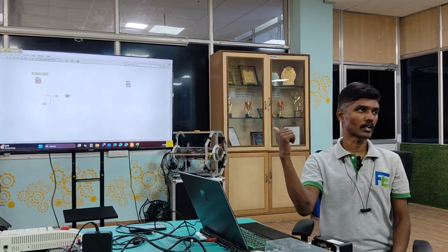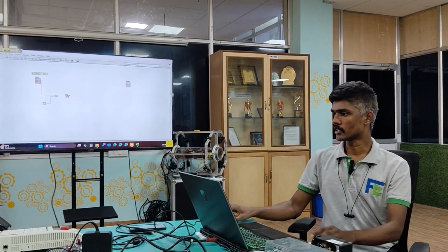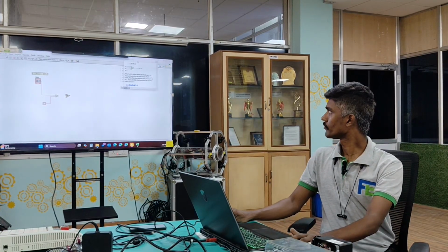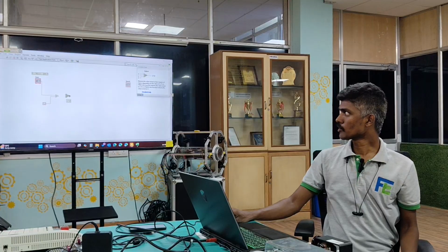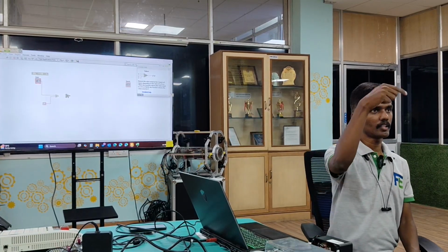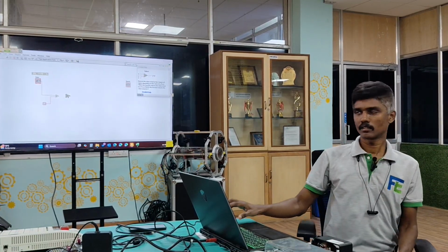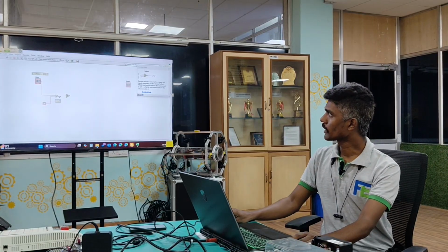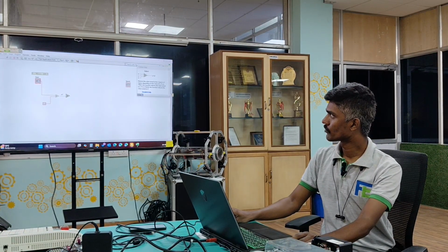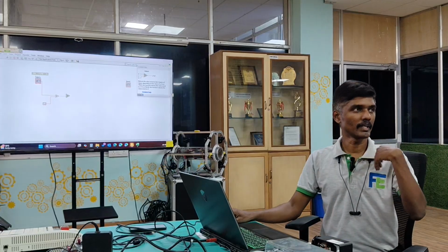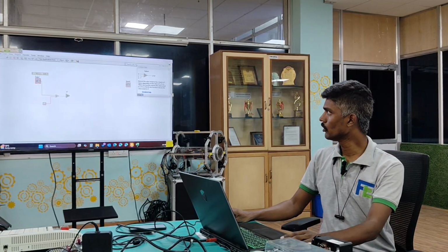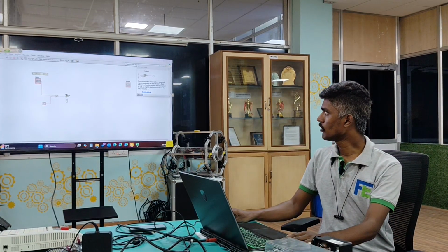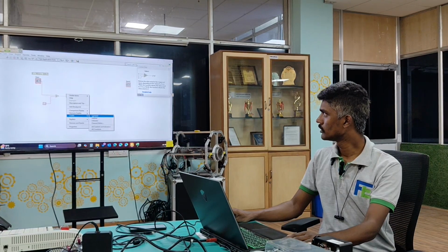and if you don't know how to work with this block, press Ctrl H on your keyboard. So it is giving a small description. It has 3 inputs: true, false, as well as the signal. Signal you will connect from your K structure value. If the condition is true, my gain value is less than 1.2, I will always enter the value as 0.